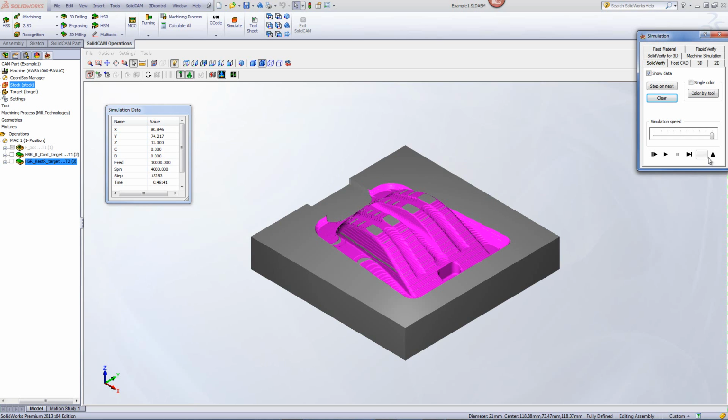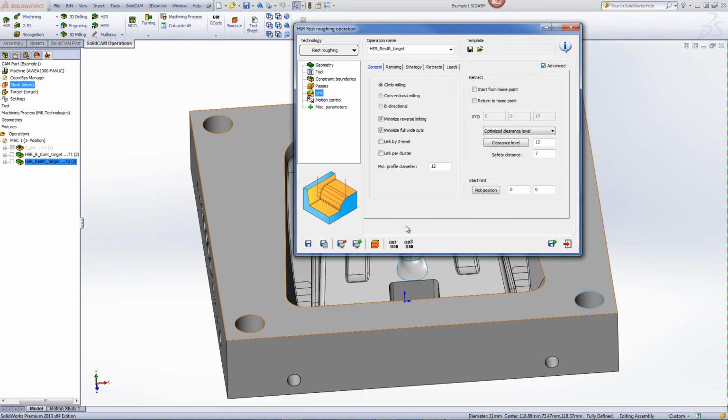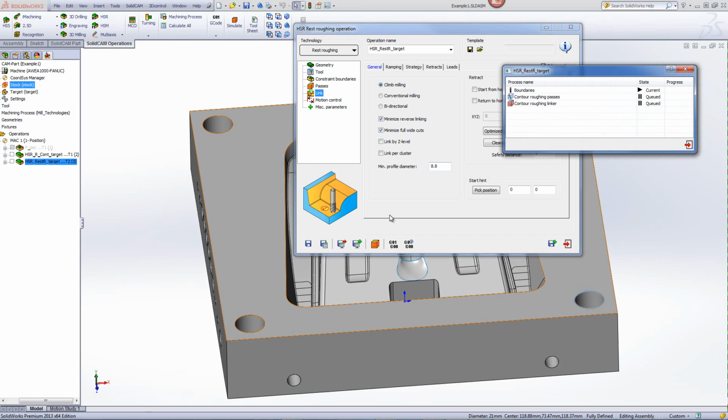So this actually can control large areas where you don't want the tool to go into, just by upping this value or making it lower. Putting it back at the default, reset this parameter, it's 8.8. Okay, again I'm going to do save and calculate and let it finish its course.